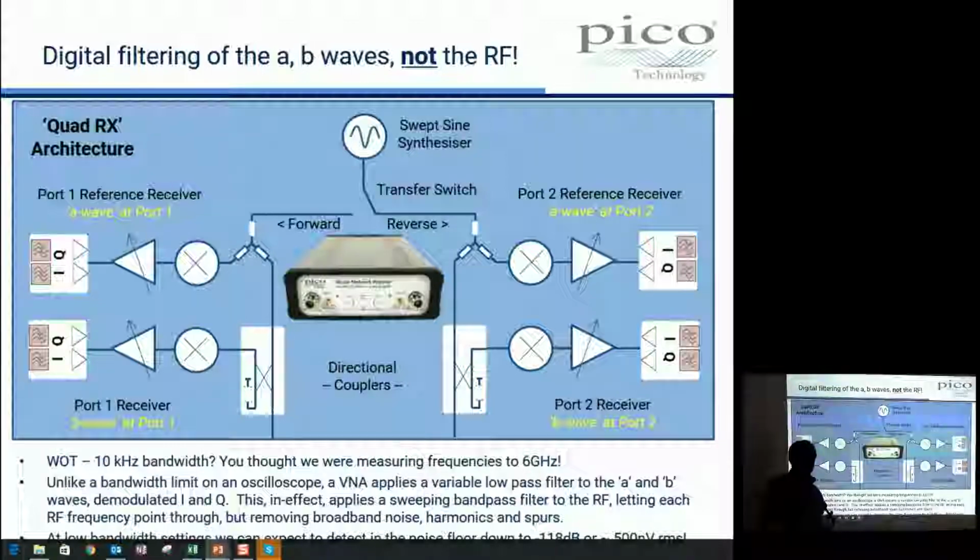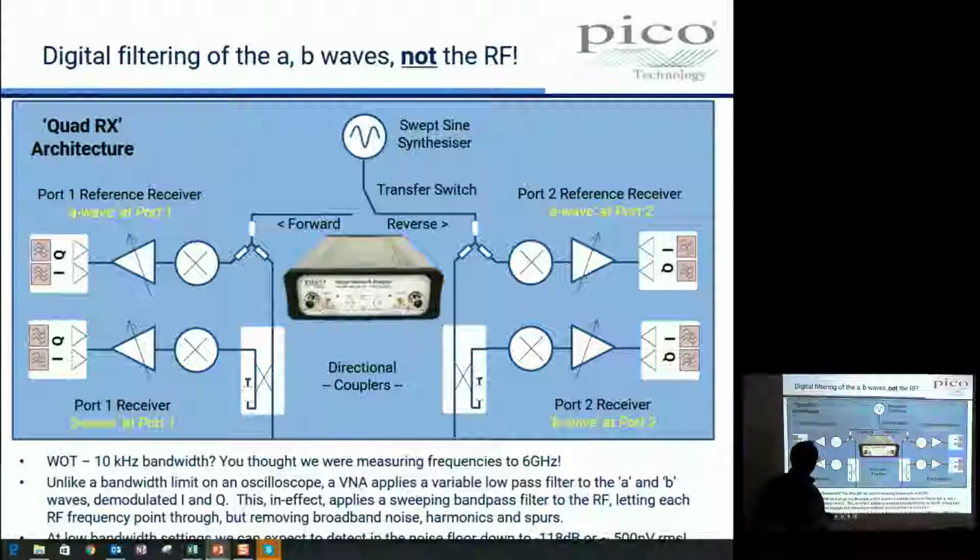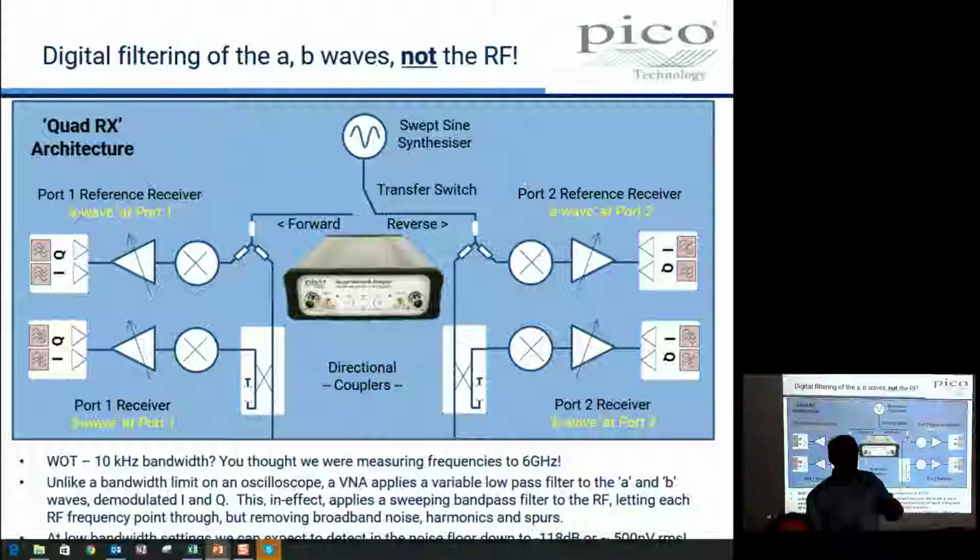So when we apply our filter, we do it not to any of these frequencies, but remember, a network analyzer is constantly calculating, say, amplitude of the vector, say, phase. It's constantly updating its network analysis into a measurement of gain or a measurement of phase or other parameters. And we apply the filter to that information, not the RF signal, not the high frequency signal. Clearly, if I applied a 10 hertz filter to 6 gigs, poof, gone, yeah, it's all gone.